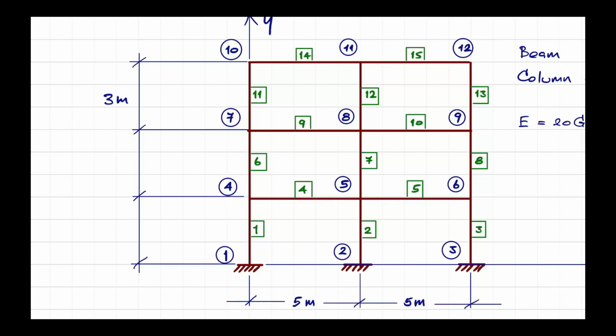Well, for the large structure, you have to rely on the graphic user interface. For a large building, you cannot afford to just put in element by element. So you use a structural analysis program that talks to the CAD program, like AutoCAD. You get the floor plan from AutoCAD, import it, and then you get the grid lines and so on, and then you can construct the model quite easily. That's the price you pay, majorly, because you cannot do things by hand, to import from architectural drawings to the structural analysis program. But the main engines are what we learn in here.